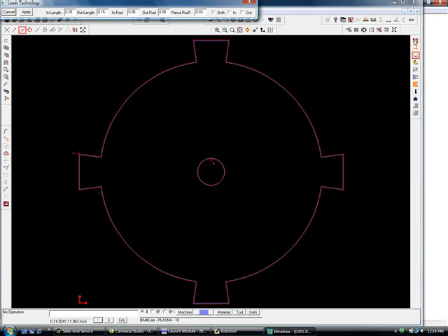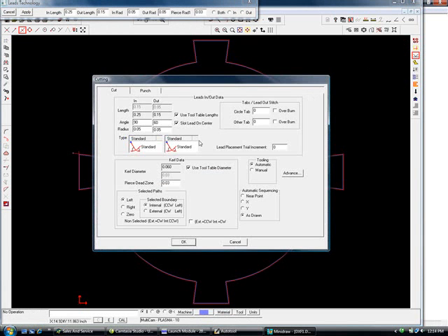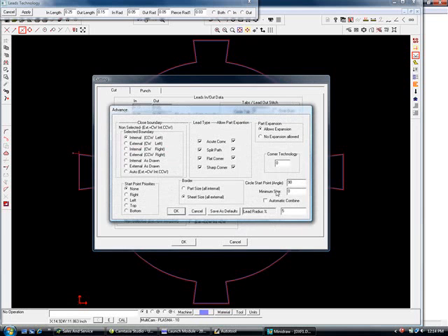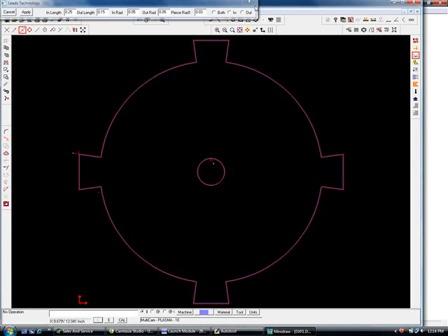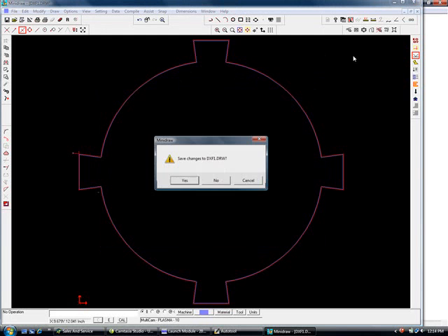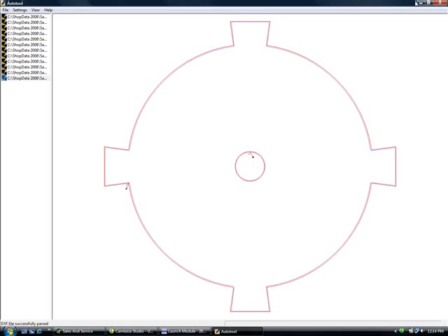On the right hand side here, apply toolpath. You can right click and it gives you control of your lead in, your lead out. You can change your angle, the radius, the kerf. We put you in the driver's seat to do things as you wish. And that is Batch Auto Tool.